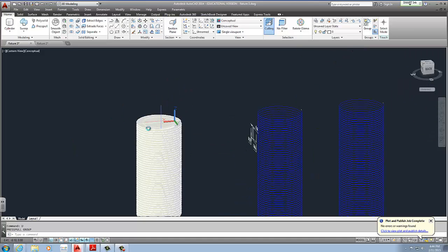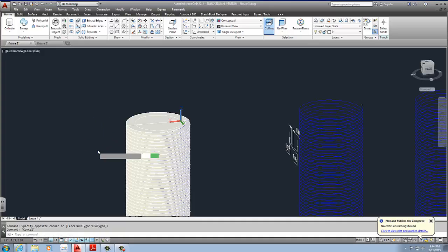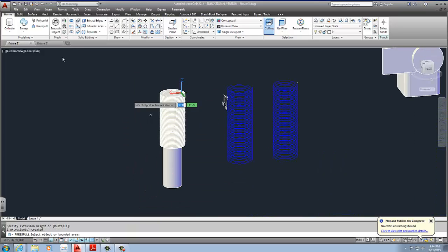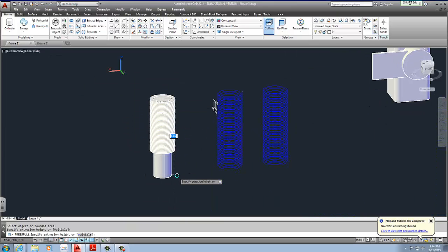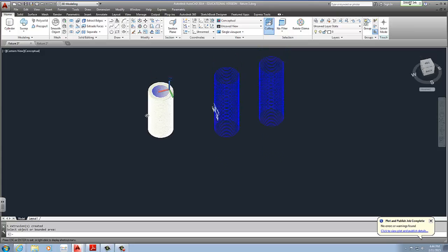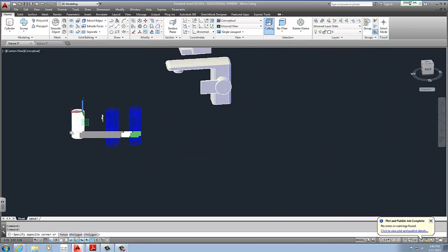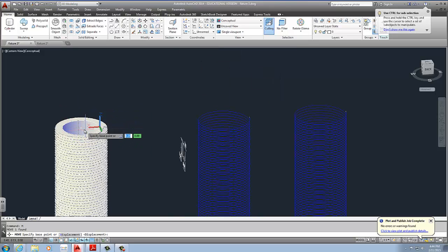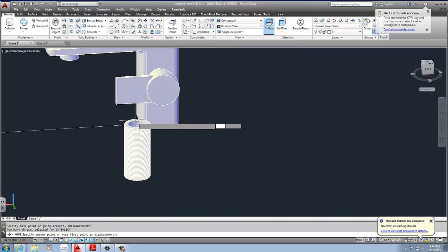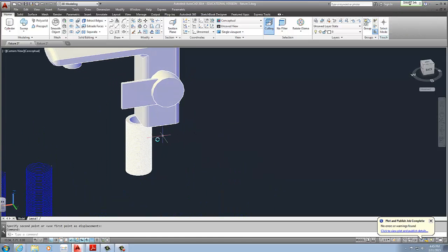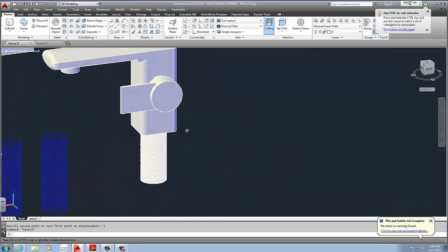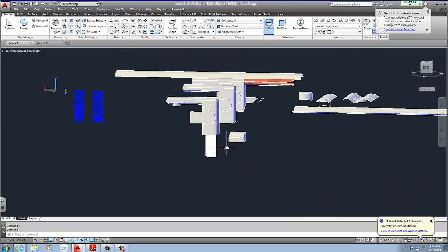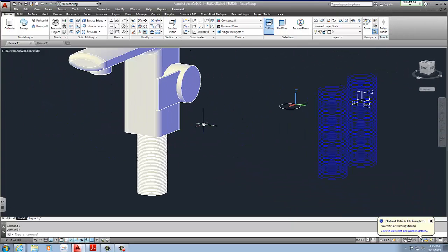Oops. Gotta delete that center line first. And that cuts out the hole for the shank. Once you have that completed, all you have to do is align this shank, which you do have a center, to the 2" by 2" rectangle or square at the bottom, and you just gotta move it 1 inch over. Since it's 2" by 2", 1 inch will be the center of it. Creating your fixture.